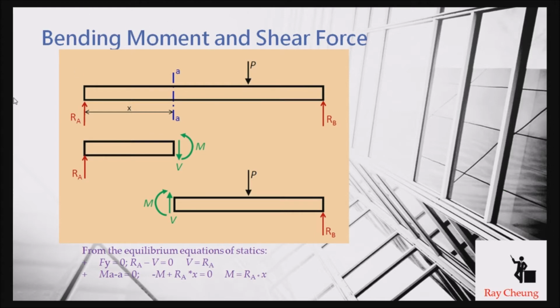The middle one just cuts the left-hand side into two pieces, and you can see we only have the reaction force, and then the middle side is a shear and the moment. And then the right-hand side is also the same, because you can understand upward force is equal to downward force, clockwise equal to anti-clockwise, and then the right-hand side should be the same.